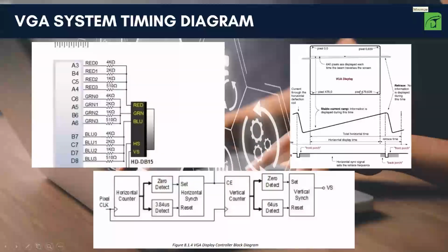This is the actual flow diagram. Before we proceed with that, let me show you the actual coding format which I was describing, in a visual manner. Here is where my first pixel address starts, from 0 to 639. For every 0 to 639, you have to count 800 pixels, in which only 0 to 639 is your actual horizontal display time. So this is the format where you present your horizontal displaying time for pixels 0 to 639.